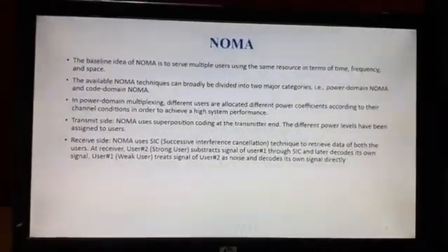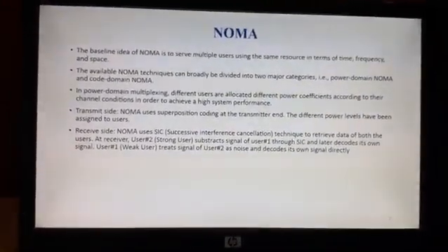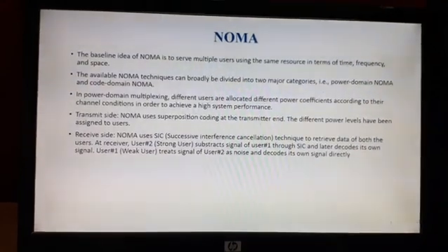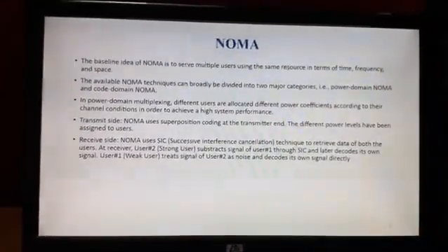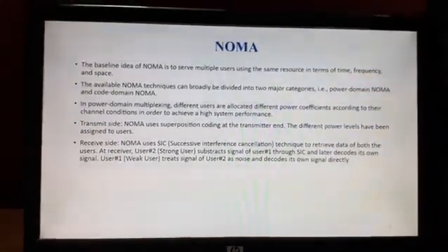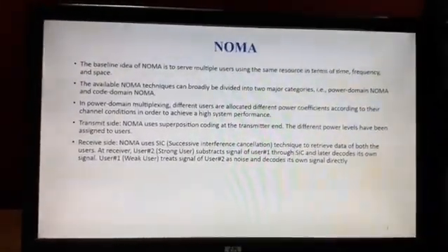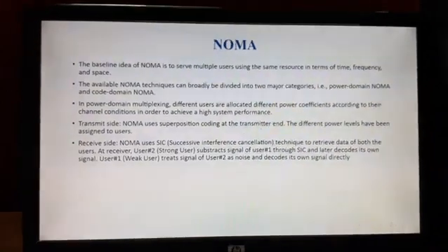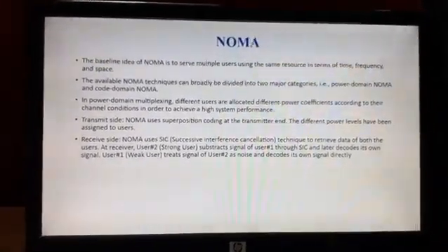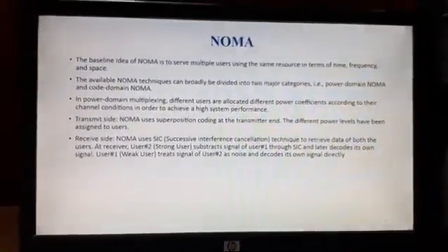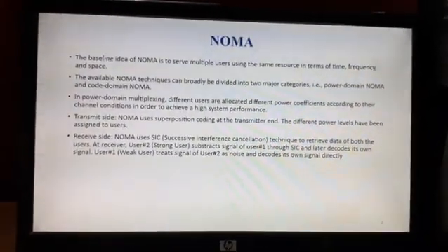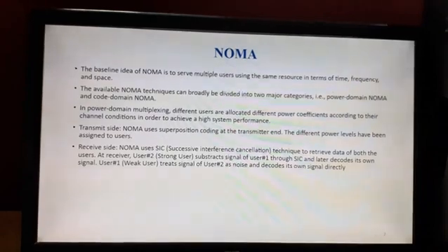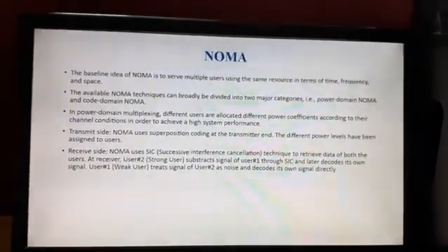The baseline idea of NOMA is to serve multiple users using the same resource in terms of time, frequency and space. The available NOMA techniques can broadly be divided into two major categories, that is power domain NOMA and code domain NOMA. In power domain multiplexing, that is the multiplexing that we are using, different users are allocated different power coefficients according to their channel conditions in order to achieve a high system performance.